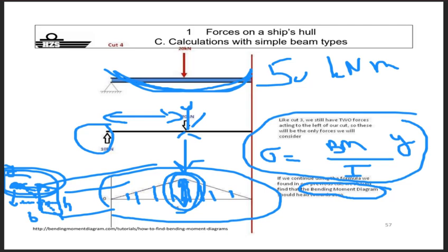Yeah, and the bending moment you calculate at 50 kilonewton meter. Y depends on the height of your beam. It's height divided by 2. Y is the height, in this case, divided by 2, because it's all perfectly symmetrical. And I is b h to the third divided by 12. And then you can calculate that stress level. And that stress level should be lower than your yield point. And that's it. That's the basic idea of today.